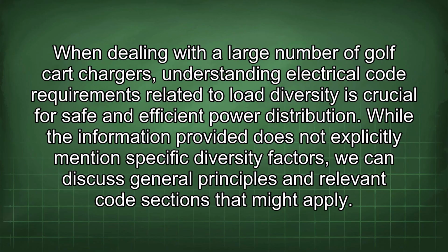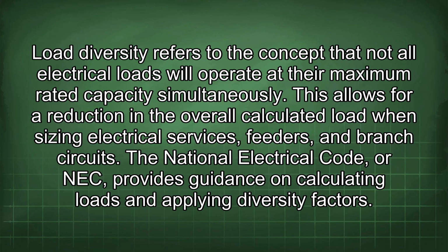When dealing with a large number of golf cart chargers, understanding electrical code requirements related to load diversity is crucial for safe and efficient power distribution. While the information provided does not explicitly mention specific diversity factors, we can discuss general principles and relevant code sections that might apply. Load diversity refers to the concept that not all electrical loads will operate at their maximum rated capacity simultaneously. This allows for a reduction in the overall calculated load when sizing electrical services, feeders, and branch circuits.